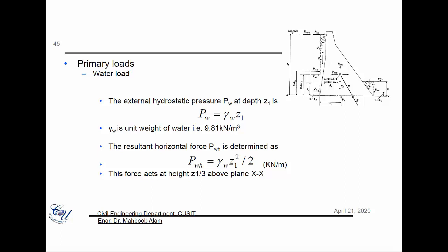And then usually we have a triangular kind of shape of the water pressure, which is minimum on top and maximum at the bottom, so we have a triangular shape. We'll be looking at this now and it would be clear. At the bottom the maximum pressure is there, gamma of water times the height of water, and then we calculate the area of that triangular region, and we calculate the total load on it.